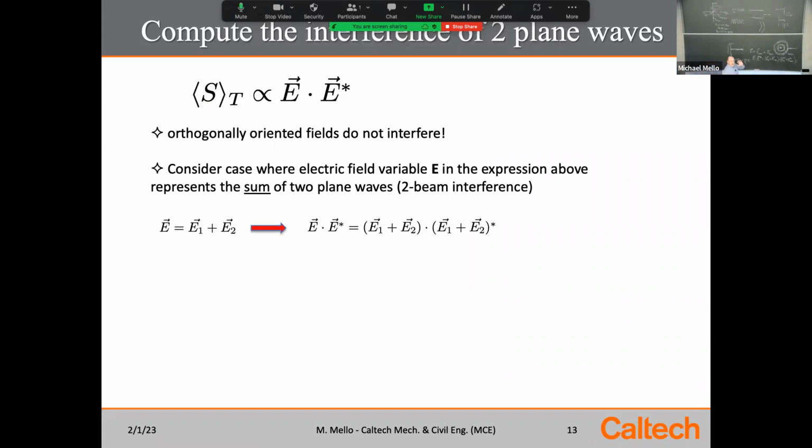And we'll do the most general one. Okay, so this is what I've just written on the board. Our photodetector of our interferometer, our vibrometer, is going to receive two beams mixed appropriately and collinear and concentric. Remember I said that at the beginning? They all get aligned so nicely and they superimpose on each other and they have E1 and E2, and we'll just start following the mathematical recipe of the E E conjugate.